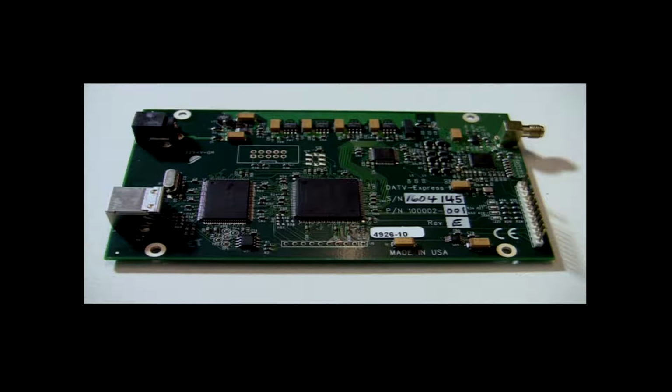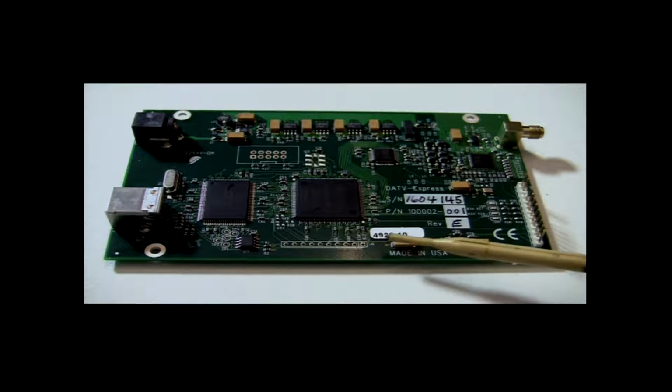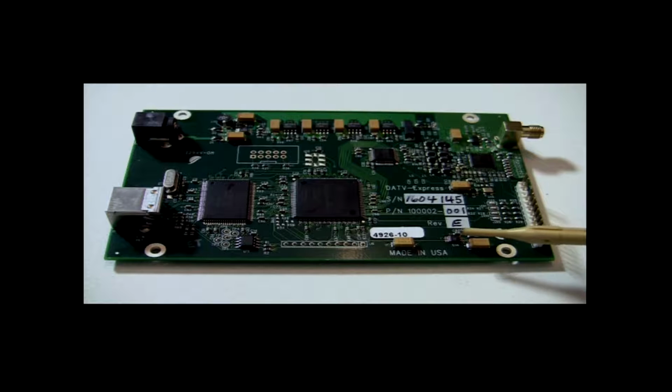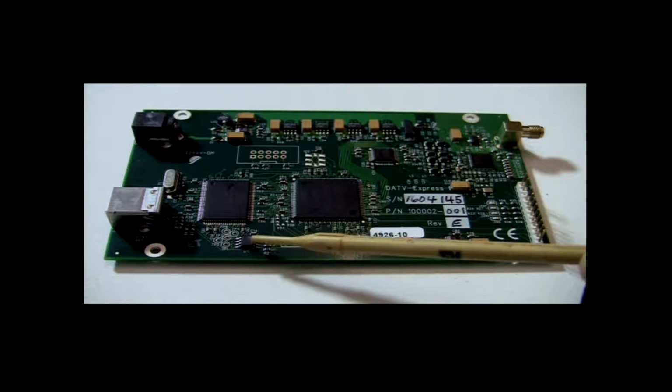First, we have the power input, which can be between about 8 and 15 volts. Then we have the power regulators for all the onboard chips, the USB 2 interface and its associated crystal, and the USB 2 controller, the FPGA, the D2A converter, the anti-alias filters, the VCO and IQ modulator, the amplifier, the socket, the LED and PTT lines, a parallel interface for selecting bands, unused A to D converter, unused flash.